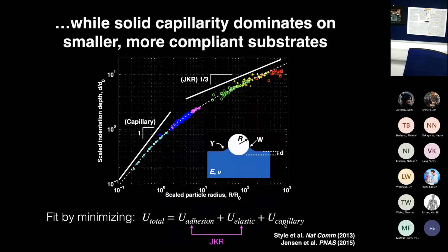Okay, so starting from here, I just wanted to note there's a crossover around an elastic capillary length scale, which is just given by the ratio of the surface stress or surface tension to the elastic modulus. So that starts to tell you where the crossover in behavior occurs, from elastically dominated, traditional solid behavior to capillary dominated, more liquid-like but still solid behavior.